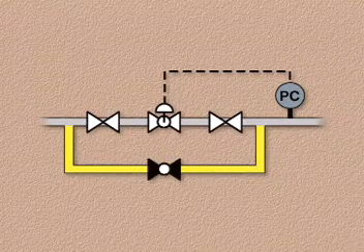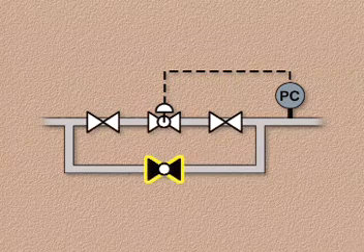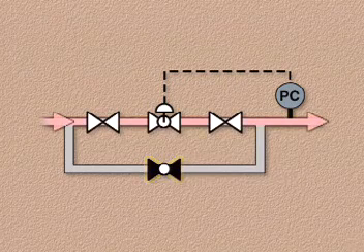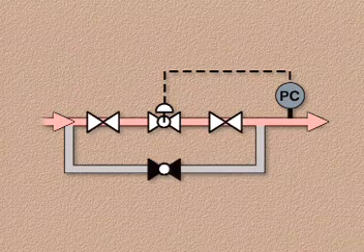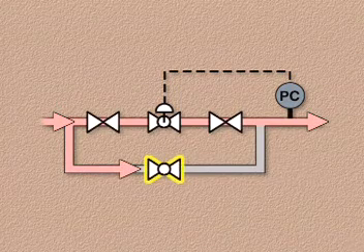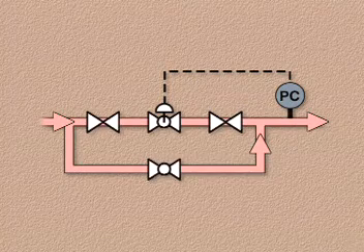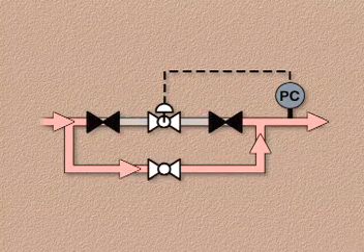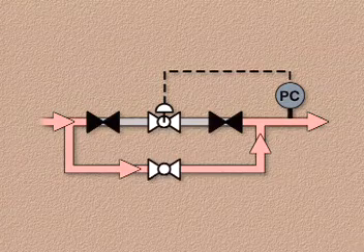This line is the bypass line. In our example, the bypass line contains a globe-type bypass valve. During normal operating conditions, the bypass valve is closed. However, the bypass valve can be opened manually to allow steam to continue to flow to downstream equipment if the pressure regulator must be isolated for some reason, such as a leak or a malfunctioning control valve.